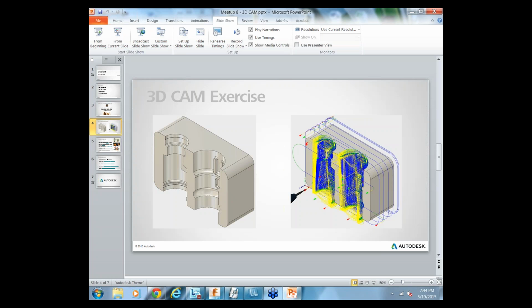The ShopBot, there are solutions where you can just take it from the Fusion file and put it into vCarve or something like that, right? You export it, you don't have to use the CAM interface as the interface with it. You can use one of the other ones. Oh, so I can take my model and put it into vCarve and let vCarve do the G code? You could do that, but it's a post-processing step.